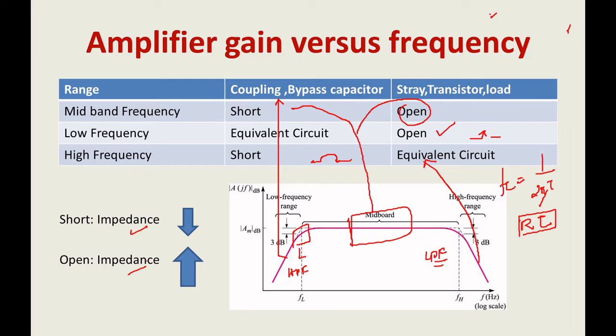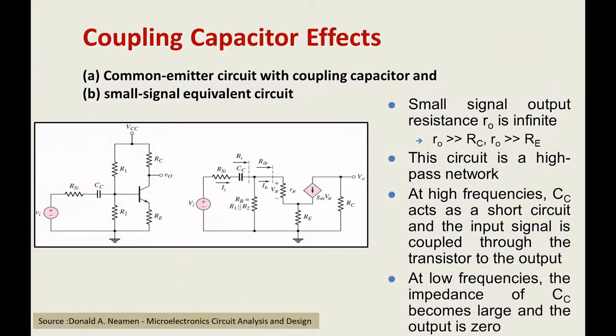With that information, we'll go to the very important part. You can see the circuit; observe it clearly. I have considered the coupling capacitor in the model also, because I want to study the working property of the input coupling capacitor, and I am going to derive the cutoff frequency for this coupling capacitor effect. This is a divider biasing, R1 and R2. This is a DC supply.